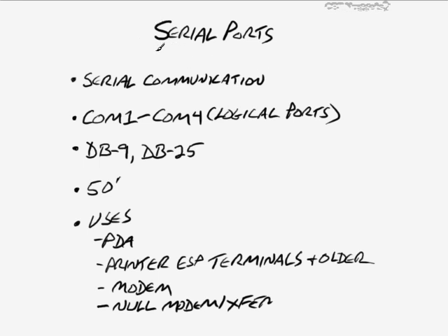These are actually known as serial ports, and that's because of the way that the serial communication takes place. The source of the communication might be a modem or some kind of data transfer, and it just goes serially, in other words, like in a single file line. And this bit of data does not get transmitted until this bit of data has already been sent and has been received on the other end. So it's all data that goes in a single file line, so to speak.